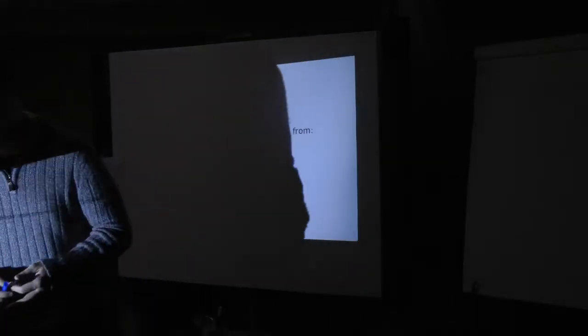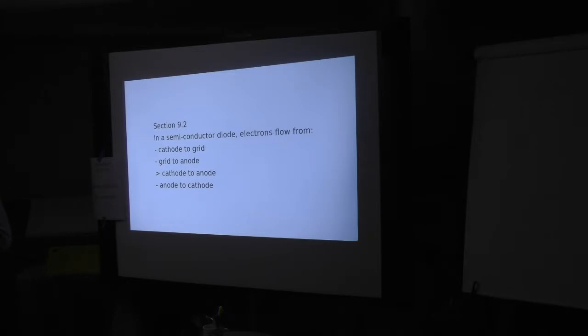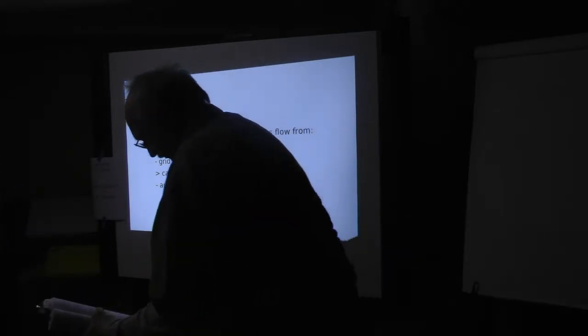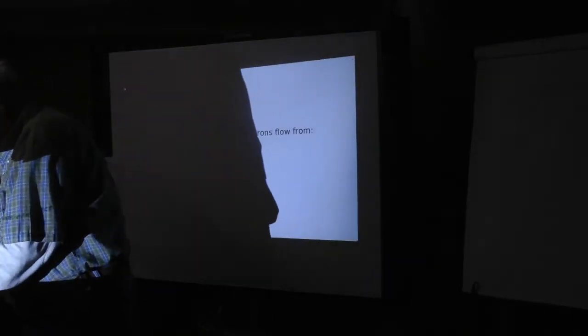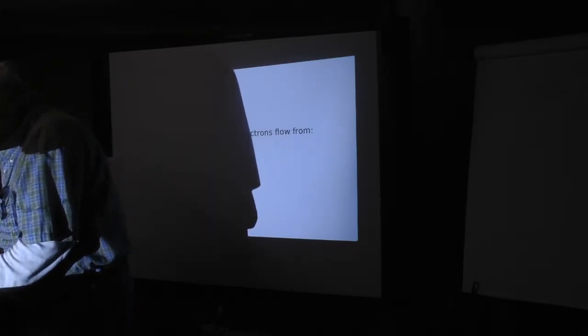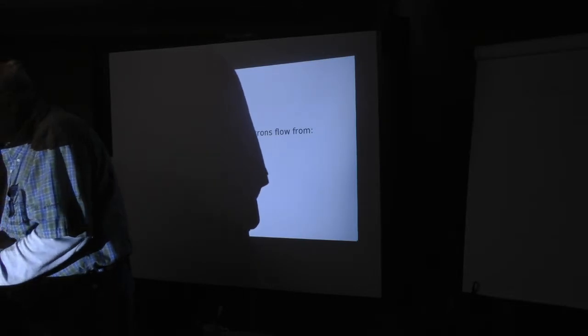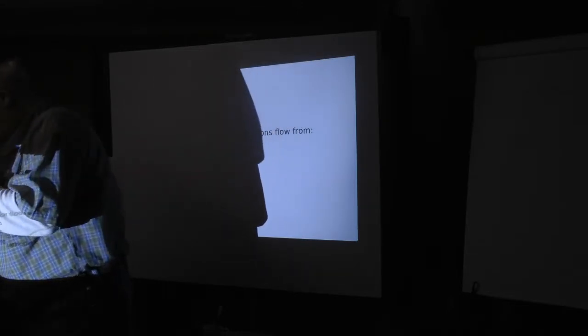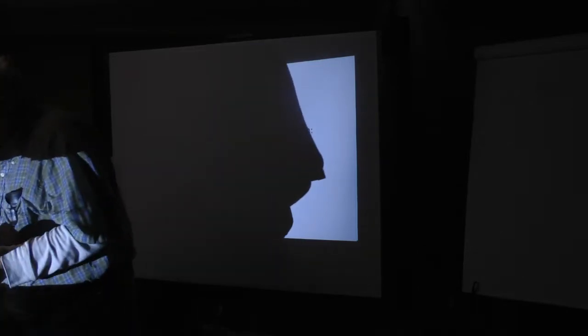Alex, if you want my honest opinion, I always get confused. A lot of times I put a diode across a small coil to stop the back EMF. I hook the coil up to the correct polarities, because I'm talking about a vehicle with a negative ground, and then I just limit the current. I put the diode one way or the other, and I look for what's taking the current, because quite honestly, I can't always remember. Yep. So you just try both ways, and you can see, oh, that's the right way. Exactly. Just try it, and if it's backward, flip it. Good catch, Alice.